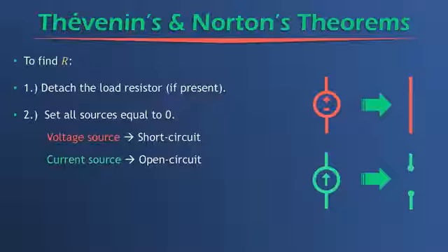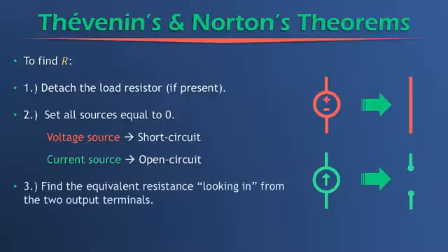And that's why. And lastly, you want to find the equivalent resistance of this new circuit, looking in, quote unquote, from the two output terminals. You can use your knowledge of series and parallel resistors and combinations of series and parallel to simplify down to just one resistor.